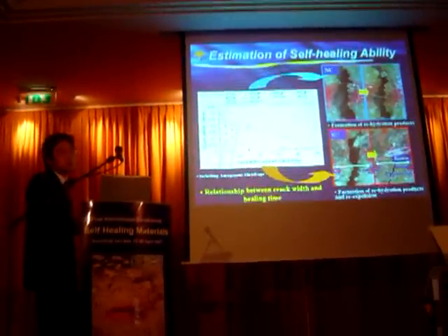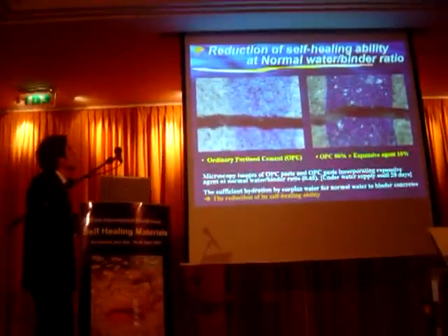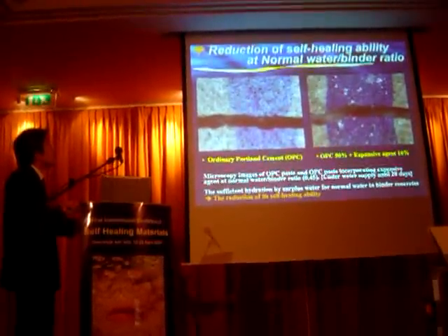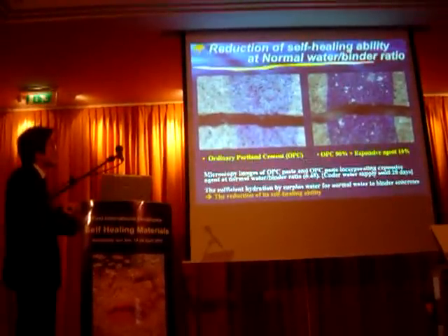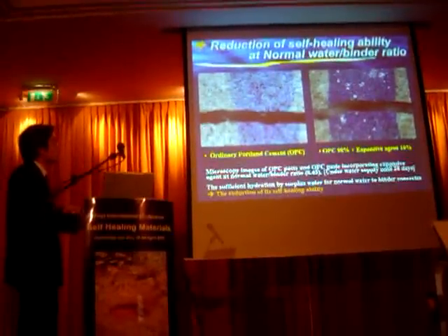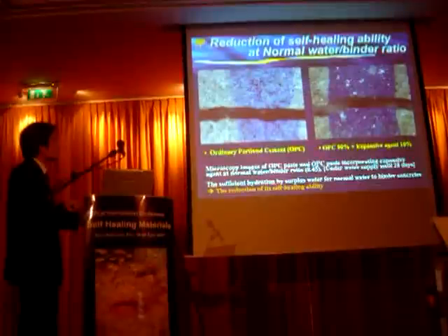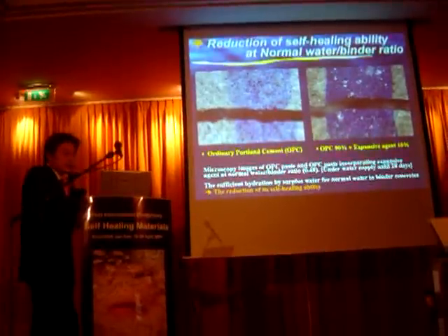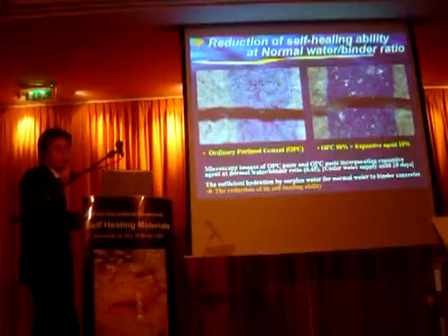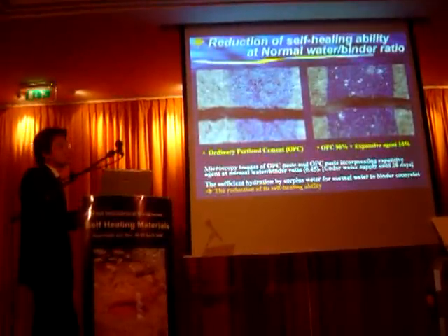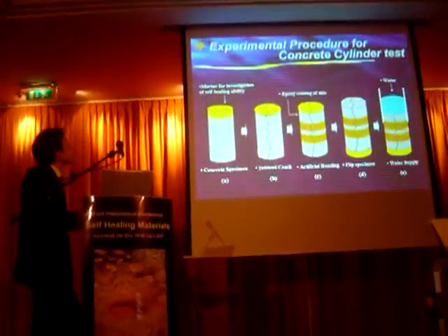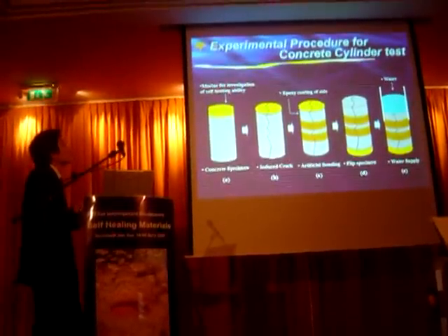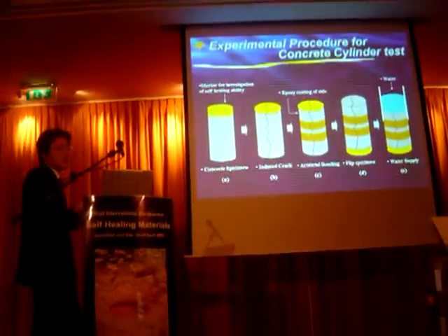However, in the case of the normal water-to-binder ratio, we cannot see self-healing abilities even though incorporating expansion agent like this, due to sufficient hydration by surplus water for normal water-to-binder concrete. So in order to give self-healing ability at the low water-to-binder ratio, we did the test like this. This figure schematically shows the experimental procedure for the concrete cylinder test using the various carbonate.